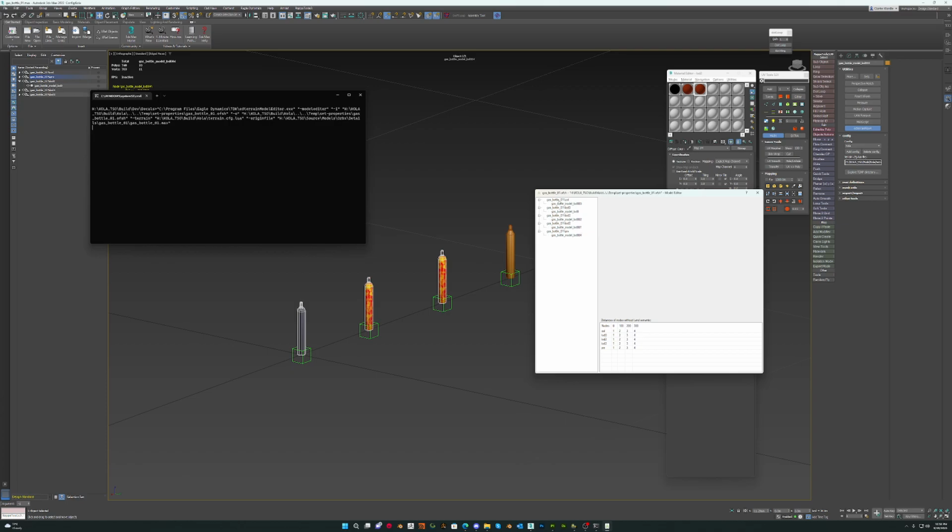First thing we'll do, on the first dummy, we'll just say that's a collision shell. Now there is a bug at the moment where if I come down here, you see that's a V-Ray House 5.1 as a residue from a previous model. So I'll just clear that out because a collision shell mesh has no settings at all on it. Okay. Now if I click here, you see it's automatically set this as a collision shell, which is not true. That's a bug within the TDK and should be fixed in 1.8. So if we just turn that off, okay, and this is where we set our distances.